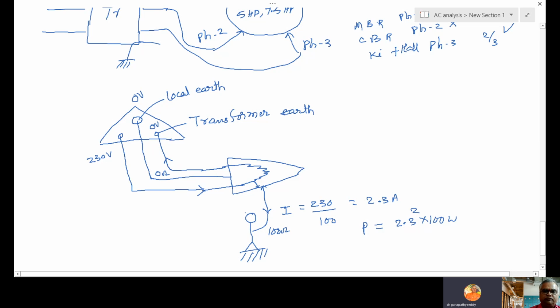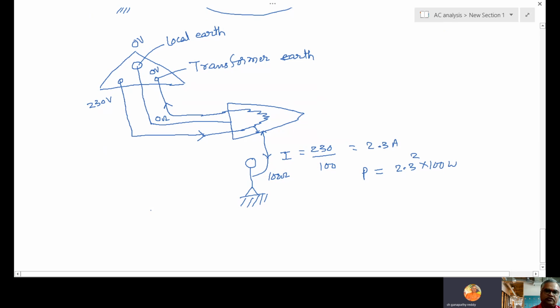We generally use 3-pin plug for iron box, washing machine, geyser, AC, grinder, etc. Where load is high and where human being is touching. Tube light is fixed in the ceiling, so we don't go for 3-pin for tube light or a bulb. And any electronic appliances, computer, charger, all these things, 3-pin not necessary. We don't get any shock.